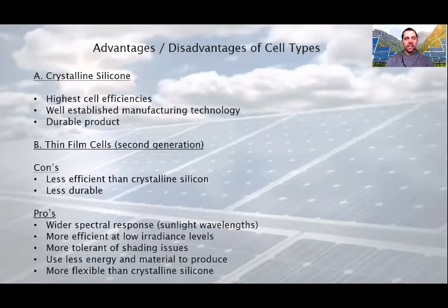But let's see their advantages. They have a wider spectral response in sunlight wavelengths, so they can utilize the rising and also setting sun's energy. So they are more efficient at low irradiance levels. They are more tolerant of shading issues. The crystalline versions aren't grateful for partial shading.